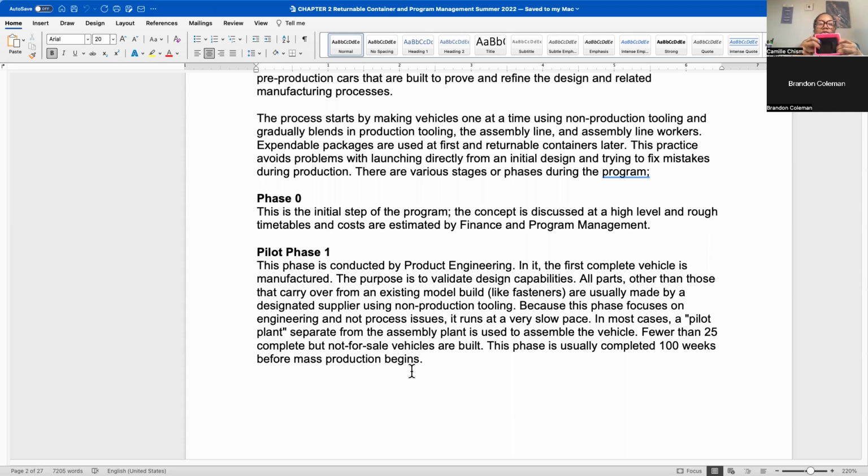And are you going to require tooling? You're going to have dunnage that's going to require tooling. So if you put a foam insert in here, for example, are you using a foam that's cut and fabricated to shape, or are you using foam that requires tooling and a mold for it? If you require tooling and a mold for it, that's going to add to your budget. So those are things that you need to look at.